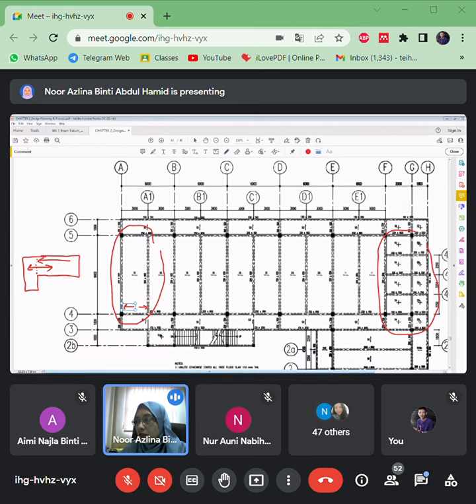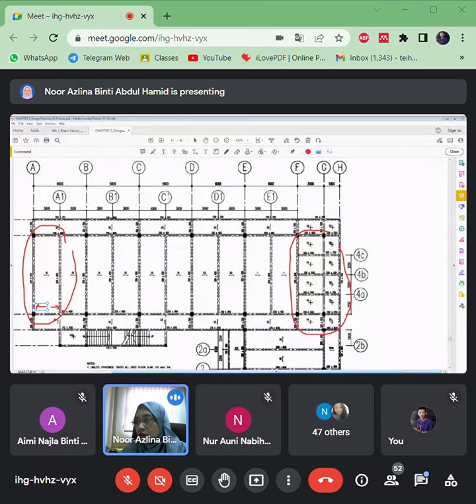So if you see here, it's a solid line, right? It's solid. That means the slab stops here, and then there's a beam that is not connected with this slab. So that means this beam just carries its own load. Okay, it does not carry the slab here. The slab will be supported by the ground level, by the soil here. Okay, so you have to be alert.